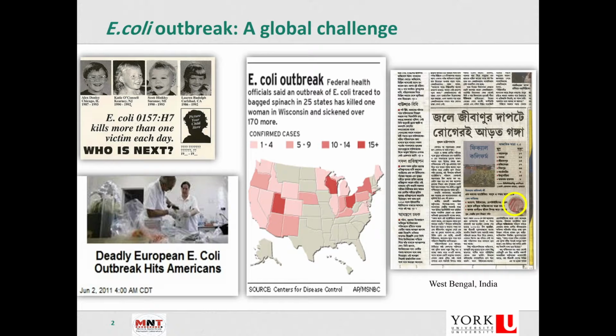There are a huge amount of contaminants, but one of the deadly ones is E. coli, which is often referred to as the kind of indicator organism. In other words, E. coli can only enter potable water through fecal contamination. So if your water contains E. coli, that means the water source has been compromised. So the chances of having other deadly things like Giardia, rotaviruses, and so on are extremely high. So that's why we target it.